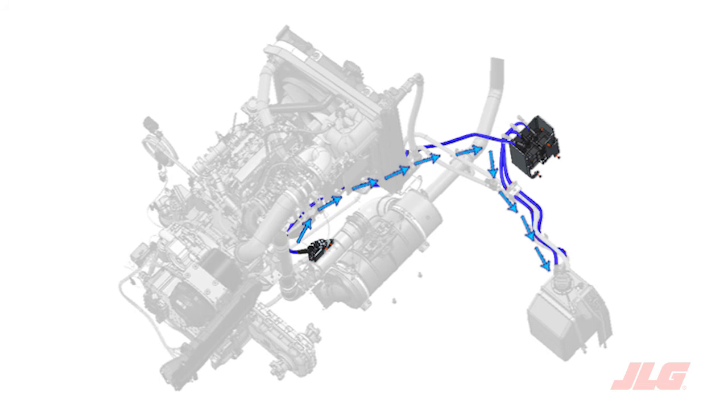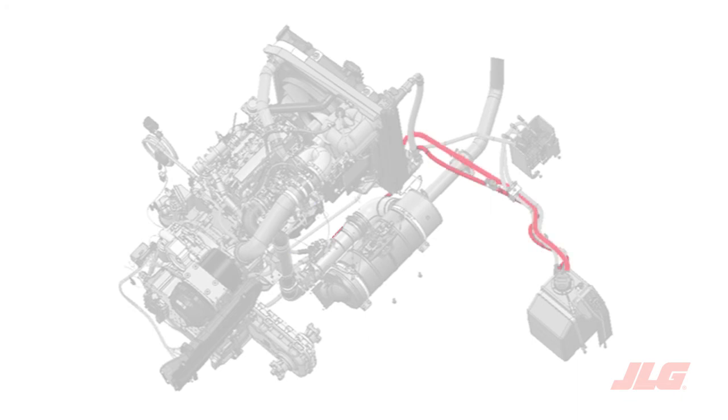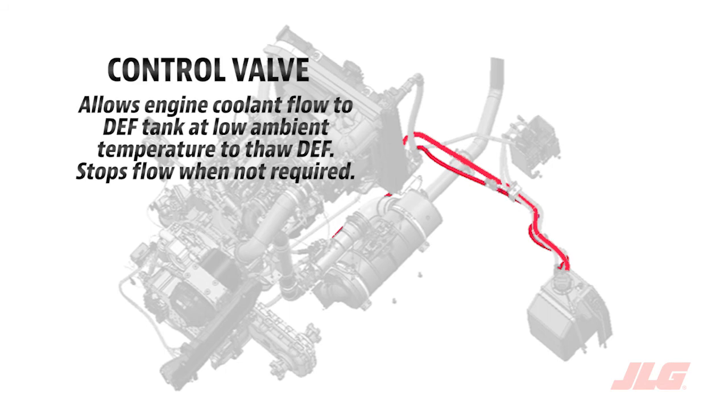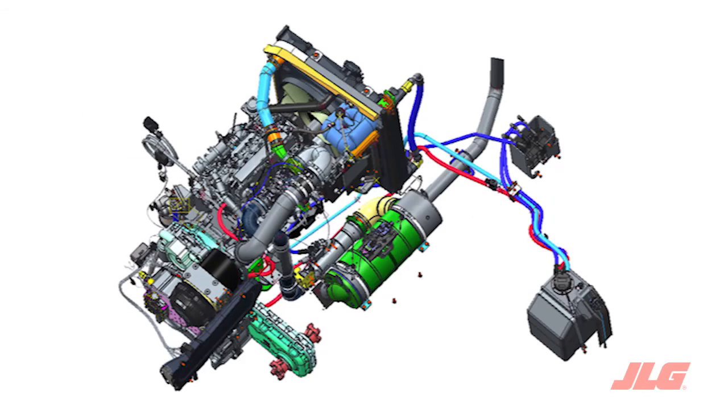In cold ambient conditions, a heating loop integrated into the DEF header carries engine coolant to thaw DEF and maintain temperature above freezing. In warm conditions, the engine coolant is shut off by an electronically activated valve in the engine coolant supply line. Note, though we are using coolant, the purpose of the coolant loop in the DEF tank is to elevate temperatures. Engine coolant also circulates in separate lines to cool the DEF injector. Note, the valve cycles upon each startup as part of a system check and will then be opened or closed depending on ambient conditions. This concludes the high-level overview of the forward DEF system.